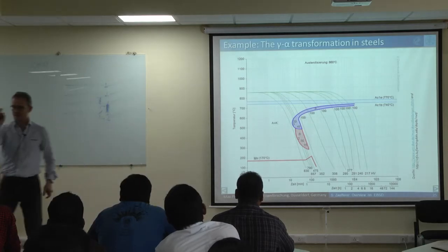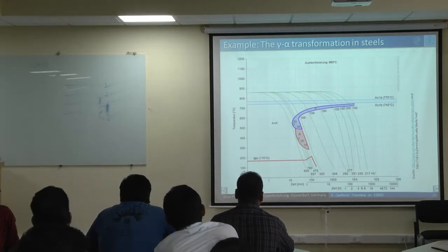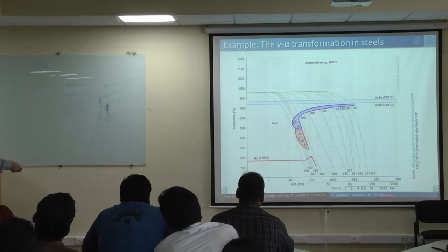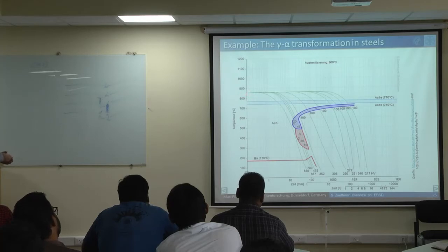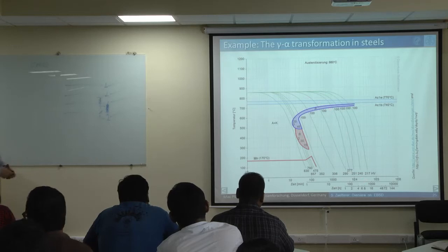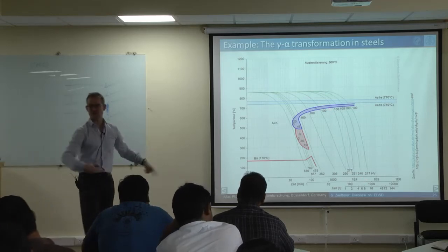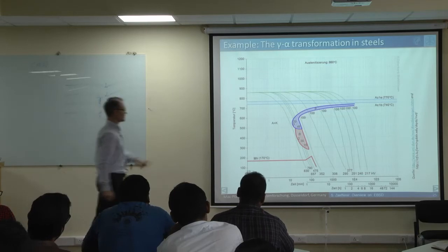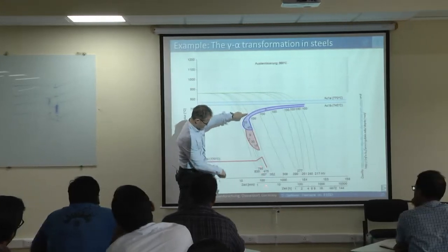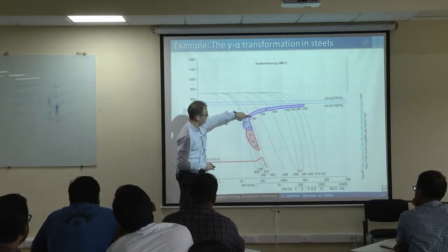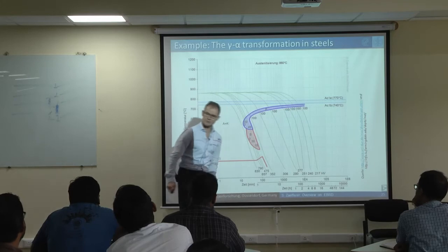I believe you're halfway familiar with the so-called TTT diagram, where you plot the time and the temperature, and then you let a sample cool down with time from a well-defined start point, for example from a perfectly austenitic area all the way cooling down to room temperature, and plotting which kind of phases are forming while the sample is cooling down. For example, when I cool down along this line here, after 100 seconds approximately, it starts forming pearlite, and then it cools down just as pearlitic.